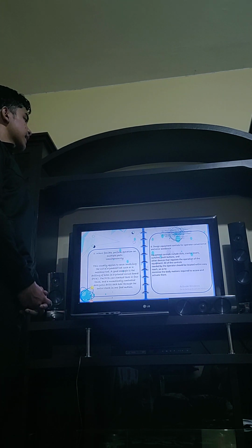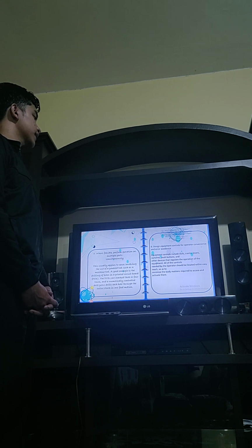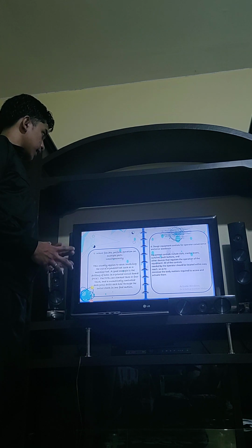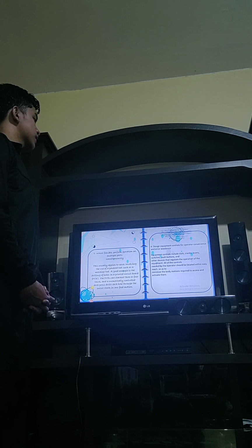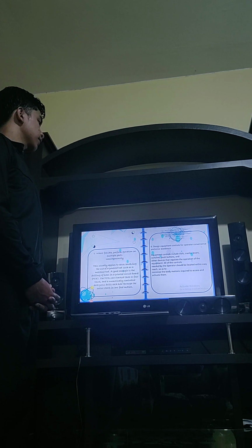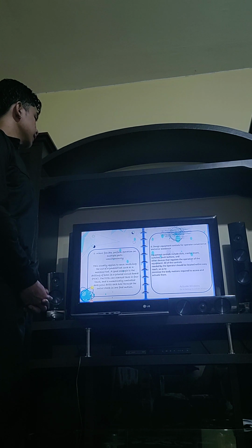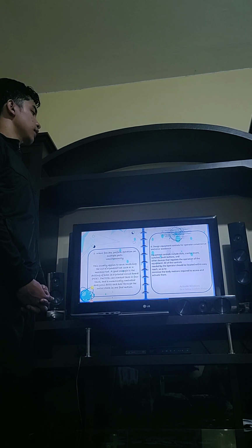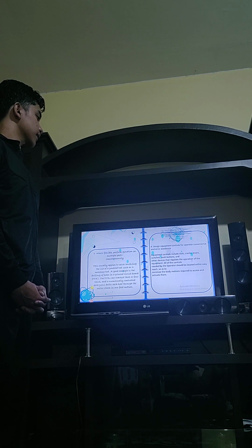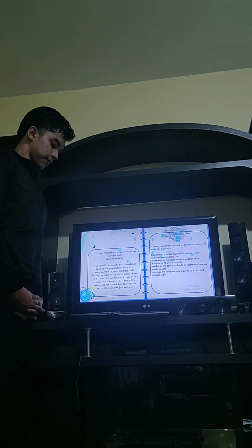Number 6. Design equipment controls for operator convenience and/or error avoidance. Equipment controls include dials, cranks, levers, switches, push buttons, and other devices that regulate the operation of the equipment. All of the controls needed by the operator should be located within easy reach so as to minimize the body motion required to access and activate them.